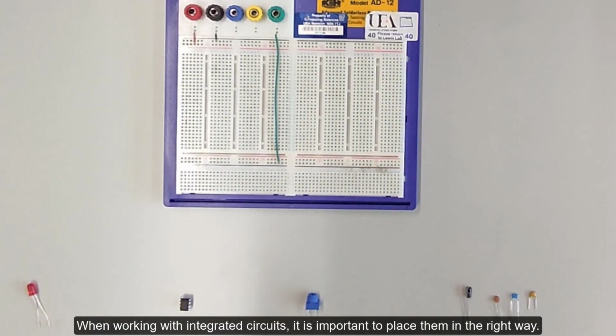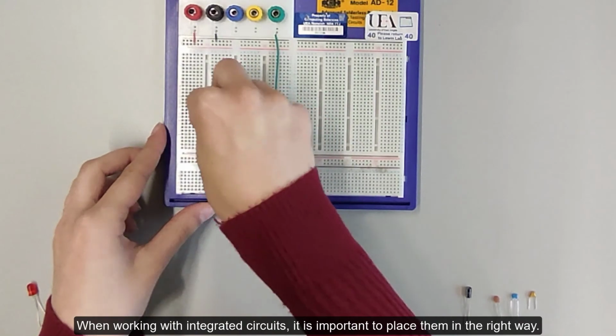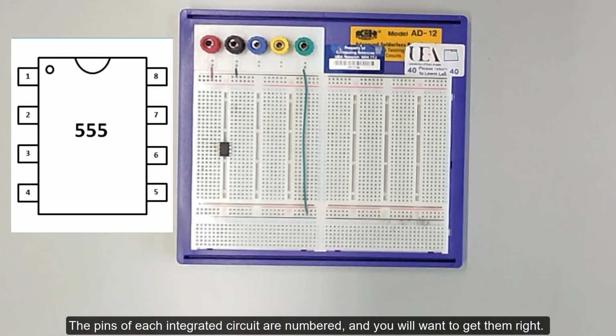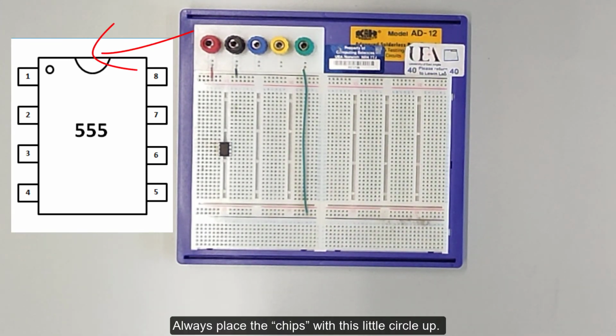When working with integrated circuits, it is important to place them in the right way. The pins of each integrated circuit are numbered, and you will want to get them right. Always place the chips with the circle up.